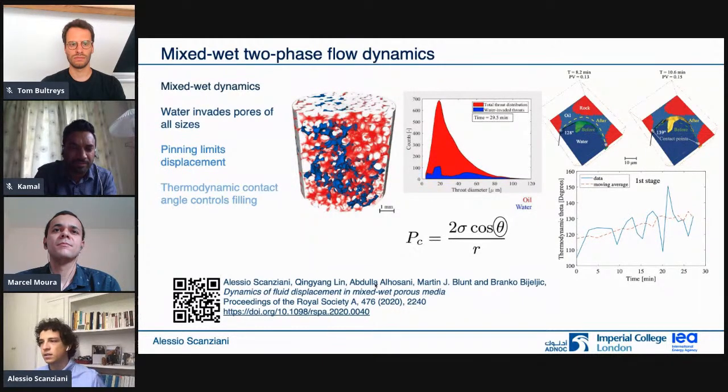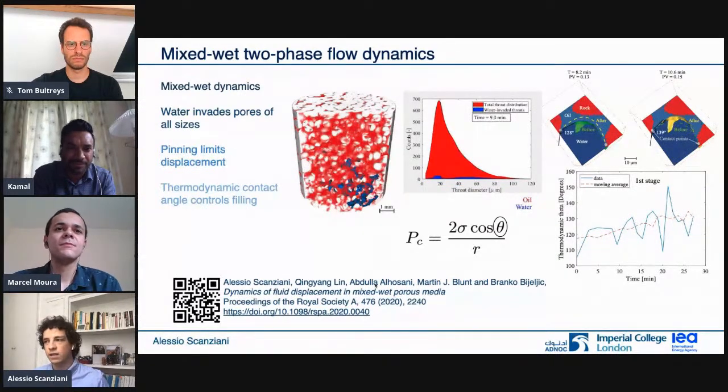The main difference that he observed at near miscible conditions is that the gas sometimes is no longer the non-wetting phase, but it can become the intermediate phase. But this is more linked to the near miscibility and not to the supercritical state. The supercritical state itself does not seem to really change much in the process.